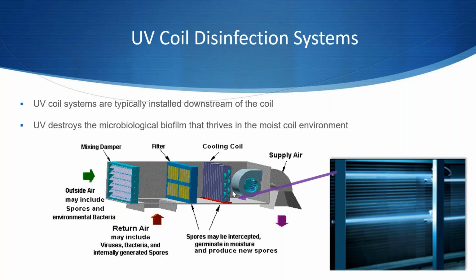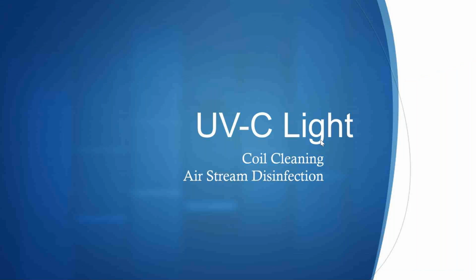But the ideal is where we can get the right velocity also. So we can go into the duct for airstream disinfection applications. We can install in parallel with the airflow to increase the residence time with the lamp. But we really need to pay attention to those velocities first to get the right dosage.